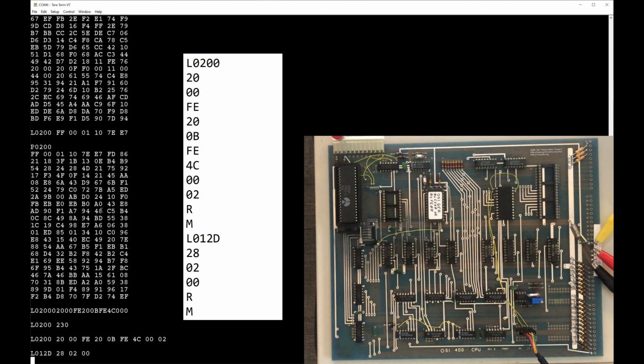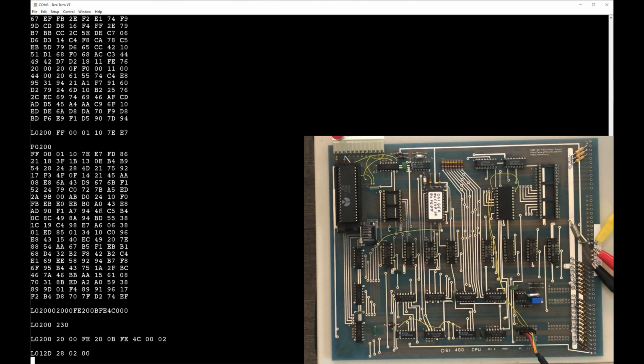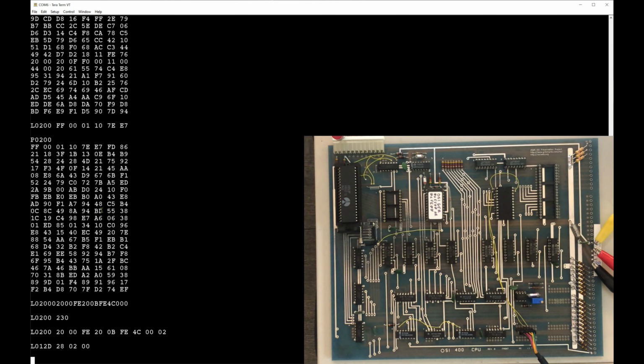And that's when we hit the go command, that it'll go there and run that. So it's going to jump to address 0200 to begin execution. I can get back to the monitor again, and now I can hit the G key, and this should work. What this should do for every key I hit on the keyboard, we should see that key echoed out twice, and we do. So this is working as expected. So that really does demonstrate the little monitor. Entering a program, dumping memory.